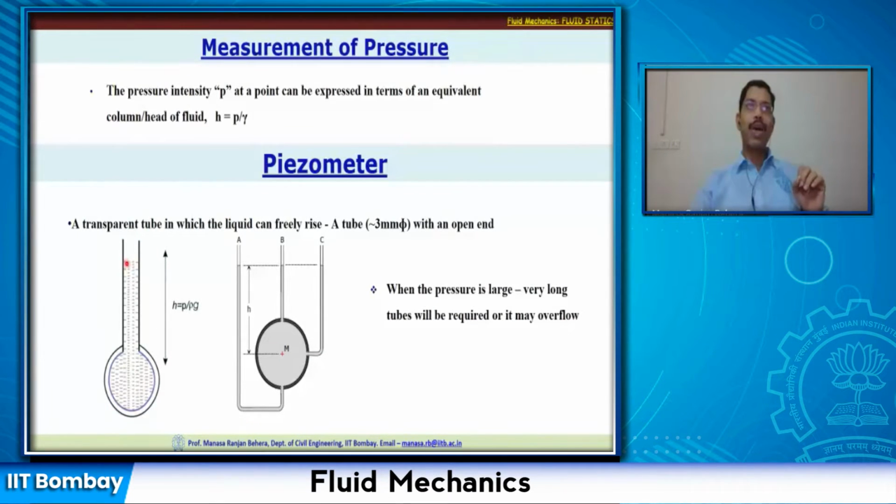So, assuming that now the total water level or the fluid level has already risen up to this, now we can find out with the scale of this tube what is the head, or what is the distance from the center of the pipe. Now, if I measure this distance, which is from this point to the point at this surface, I can take that as h.